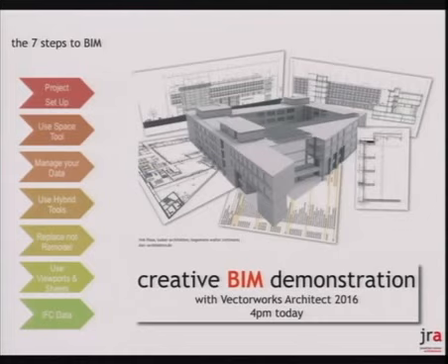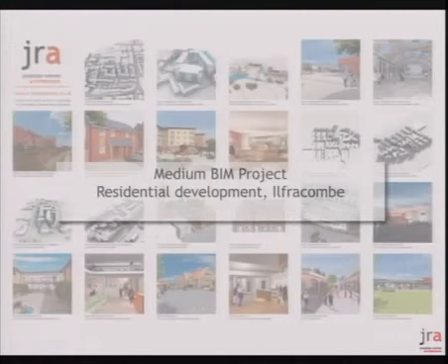What that means is the separation between the way you design something and the way you present it via the mechanism of a viewport gives you a huge amount of flexibility for the level of information and the type of information you present and show. It's one of the cornerstones of a BIM workflow, using the same information presented in lots of different ways. And finally, I might just touch on IFC and how we get model data out of Vectorworks.